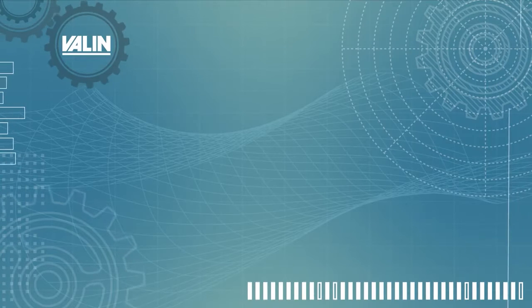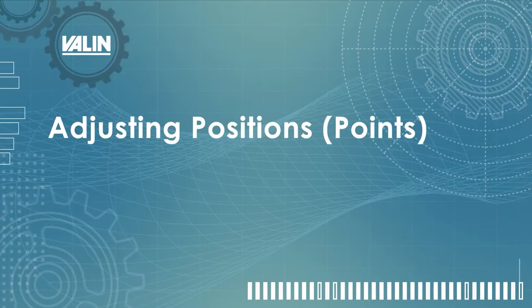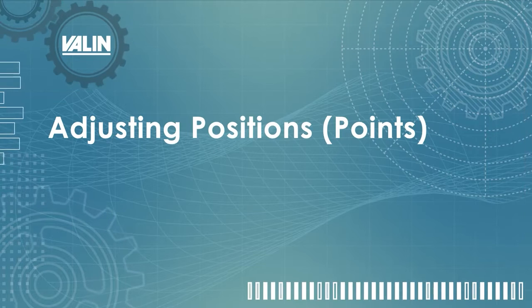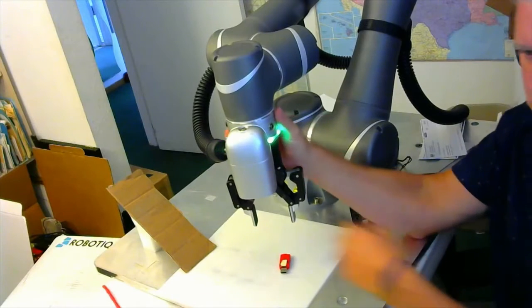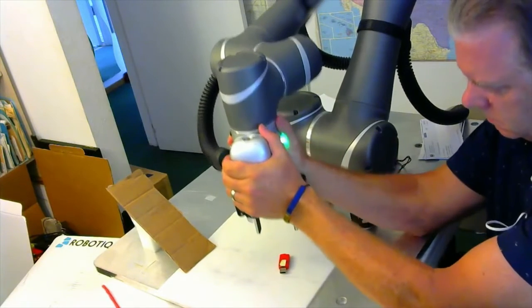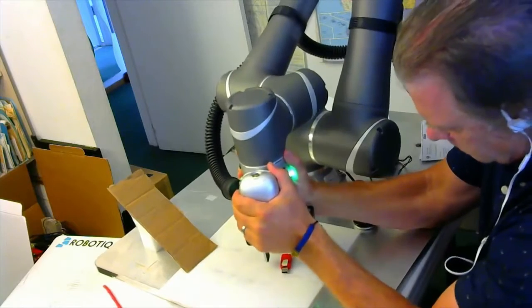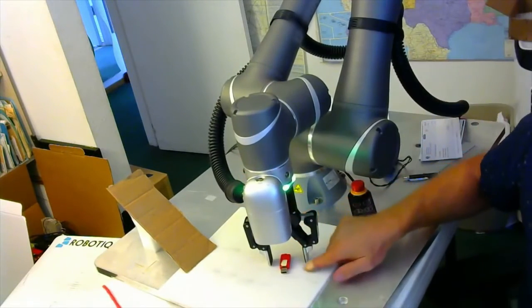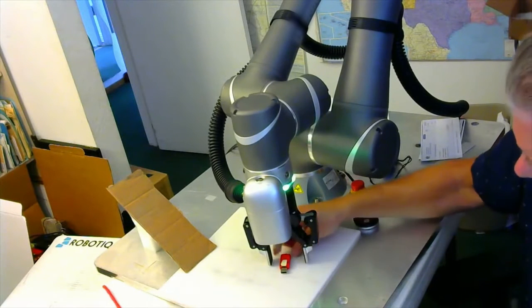The next thing I want to do is help you with adjusting your positions in case you don't get them exactly right. So we're going to go over adjusting positions on the robot, and I'll show you some manual manipulation of the robot where I'm holding the free button, and I'm going to move the robot down to where I think is a good place to pick up this part here. So I'm just holding the free button, moving it, getting it close, and I've got the Robotiq gripper, and I've just put it right parallel with the part.